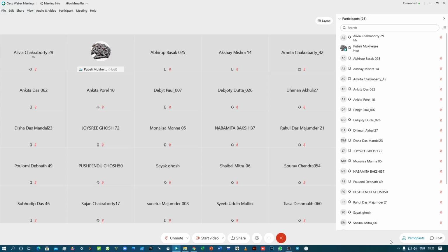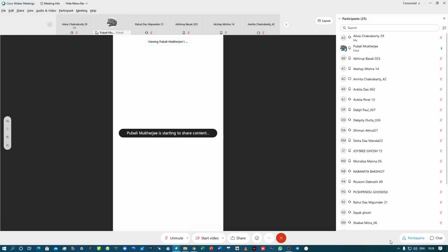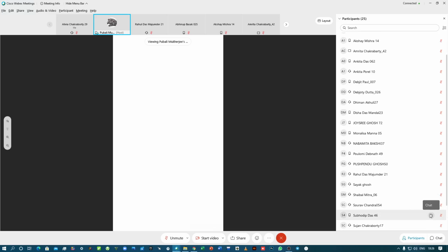Okay, so we have discussed JFET, MOSFET, drain transfer characteristics, the phenomenon of pinch-off and things like that. So more or less, we have discussed the devices. But now what we would be concentrating on mostly is the metal oxide semiconductor part of the MOSFET. The MOS part of the MOSFET, that is the metal, the oxide, that is the SiO2 layer, and the semiconductor layer.